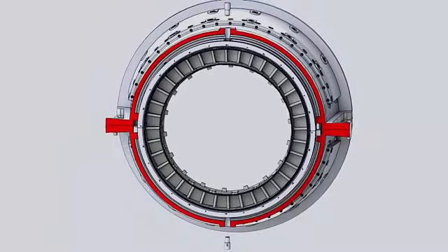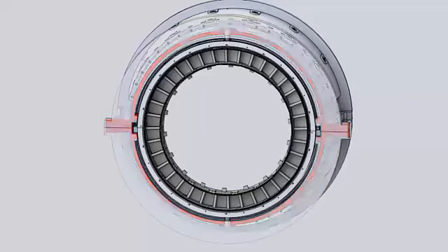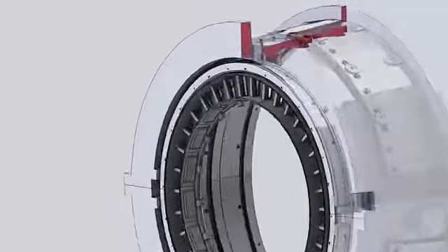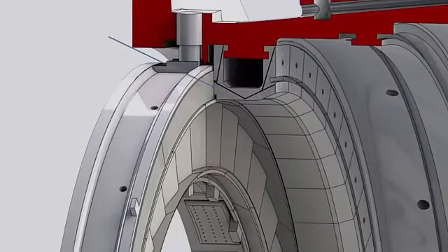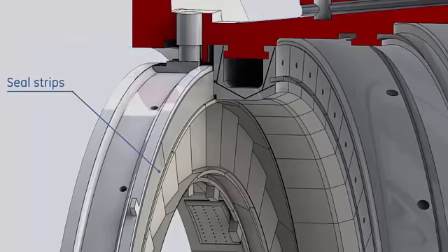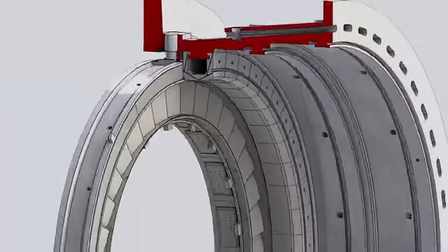The retaining ring is centered by two eccentric pins from the turbine shell. This configuration permits radial expansion due to the high temperatures encountered, while the ring remains centered to the shell. The aft outer face of the retaining ring is loaded against the forward face of the first stage shroud, with steel strips in between to prevent compressor discharge air leakage between the nozzle and the shell.